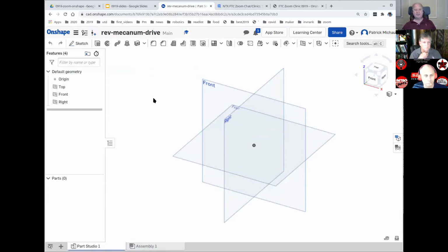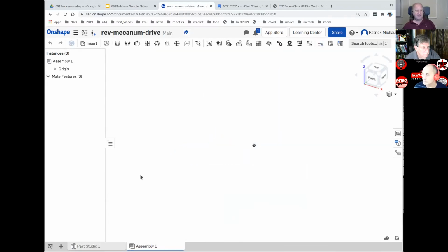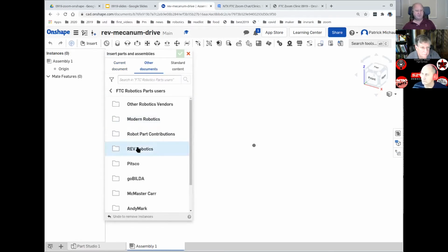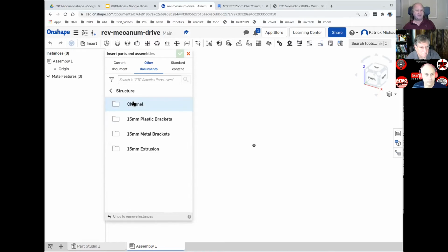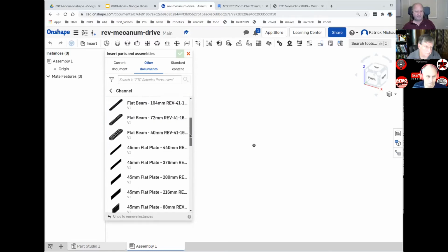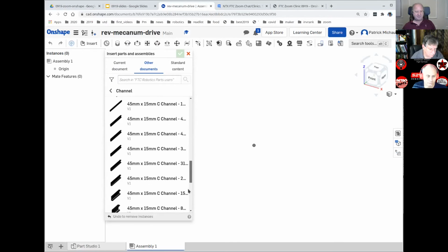All right, so we're back at the beginning part of Onshape, where I've got this empty part studio where I can design a new part, or I'm going to go straight into an assembly and start creating my assembly. And I'm just going to start pulling pieces in. So I'm going to grab the channel that's going to go across the back. So I'll go to other documents again, robotics parts, users, REV Robotics, FTC, structure, channel. And here is the channel that has been recently made available by REV. And I'm going to go down and find a piece of C channel.